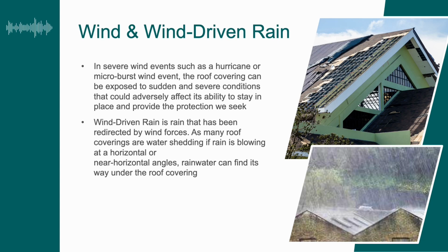Florida and southeast contractors in general see the impacts that wind-driven rain can have, because when the wind starts blowing and the rain starts blowing, it can literally blow near horizontal. And that can be detrimental to certain roof coverings, like shingles, and architectural metal that just has clips over the seams. Water can get underneath those roof coverings. That's why the underlayment is important, and considering enhancing it is a plus.